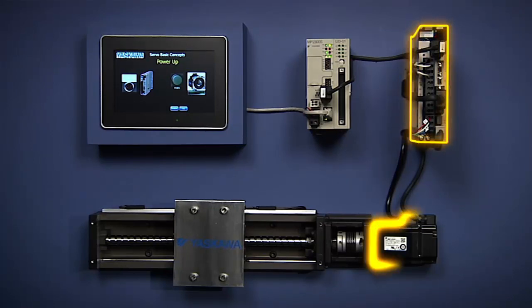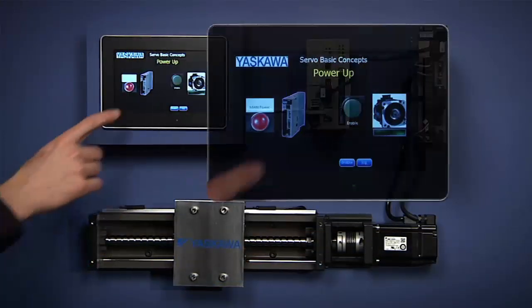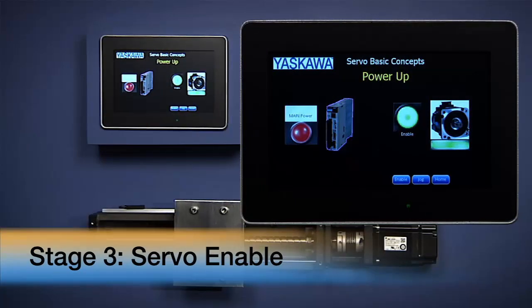The second stage is to apply the high voltage and high current power source that the amplifier will use to drive the motor. We refer to this as main power. The main power input allows flexibility in wiring to the servo amplifier. The third stage is to energize the servo motor. We refer to this as servo enable.